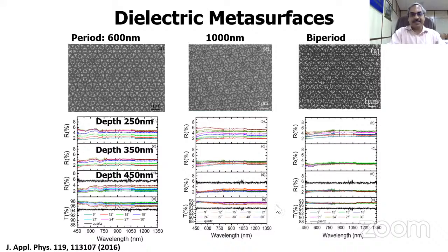I'm going very slow, so I'll quickly cover a couple of all-dielectric metamaterials. If you take a quasi-periodic structure, you take a silicon surface and make hole patterns on the top surface. These hole patterns are made to have conical shapes, with a larger diameter at the top on the surface and a lower diameter at the bottom inside the substrate. What this means is it's more air-like at the top, because more material of the substrate is removed from the top. So you have more air-like properties on the surface, and your impedance matching is working out well.